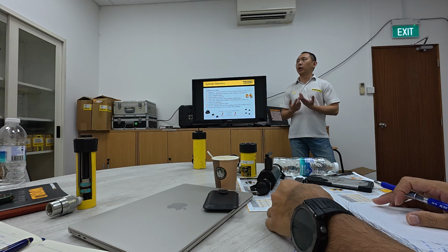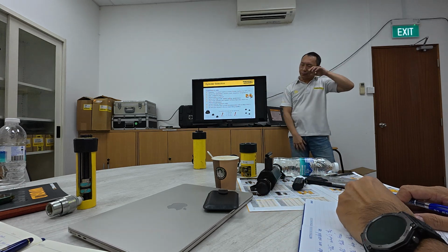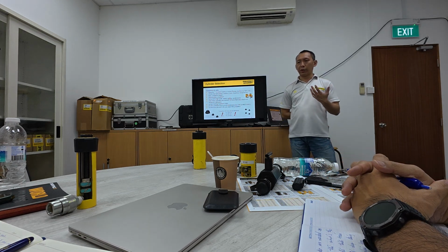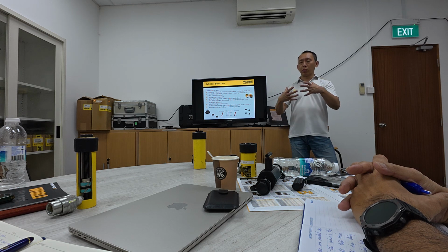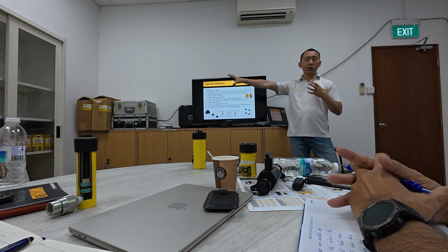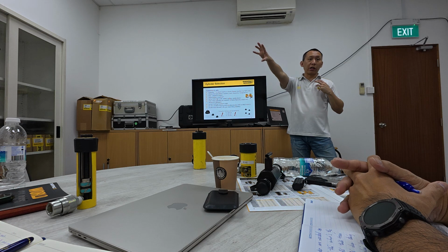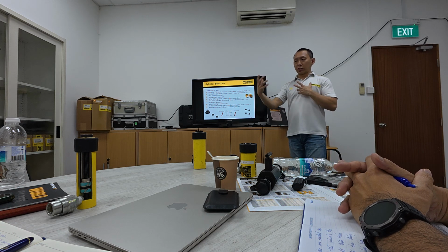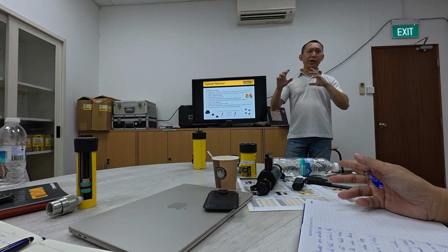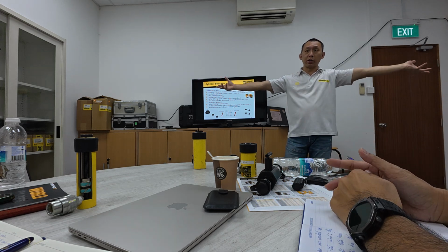For example, in a heavy lifting project, the customer has different points with different loads. Maybe at this point they need 1,000 ton, this point they need 500 ton, and the other point 200 ton. In such an application, customers may not want to buy different types of cylinder, because it's very hard to manage, and they might not need a 1,000 ton cylinder for the next project.